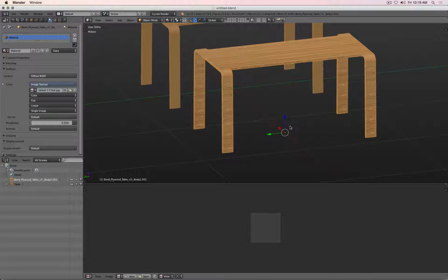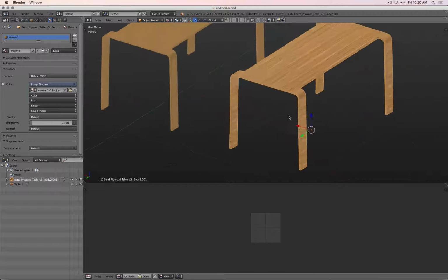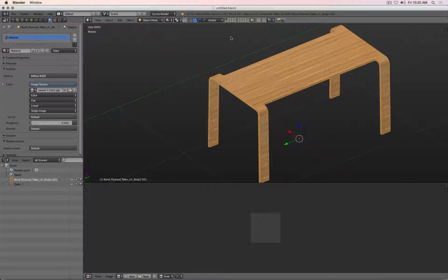Also, you only have to UV unwrap really what you need to texture with something like a wood material or a fabric material or something similar. When you do not need a texture to be projected over something, then you do not need to UV unwrap it. So if you have plastic, for example, you don't really need to do that. Or glass or steel, as long as you don't have a very specific like brush pattern on it or so. Okay, so how do we now fix this problem?